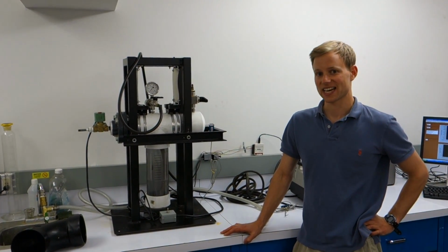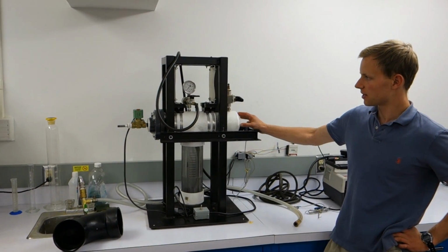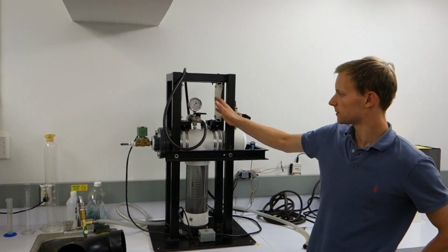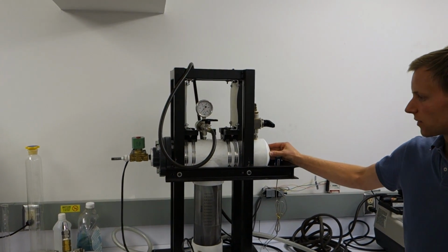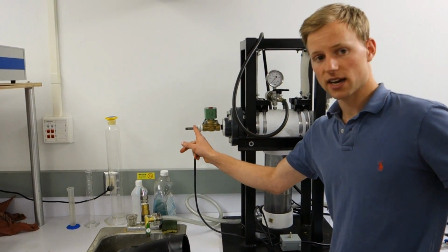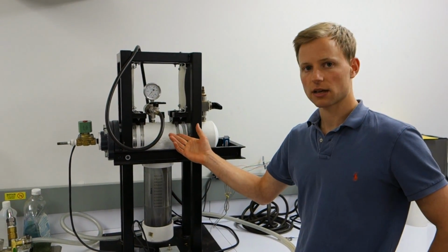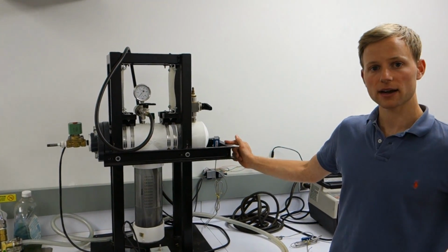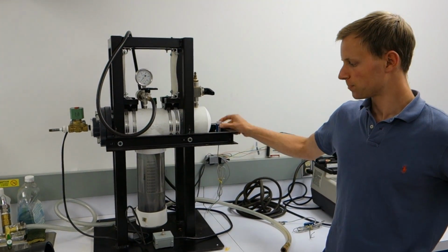Alright, so this is the water cannon. It is a rigid object held up by 2 flexible plates, which provides motion in the x direction only. What we're going to do is spit water out of the nozzle at this end, and we're going to counteract the momentum flux, which would cause an acceleration, via a reaction force on the back, which we'll measure using a force gauge here.